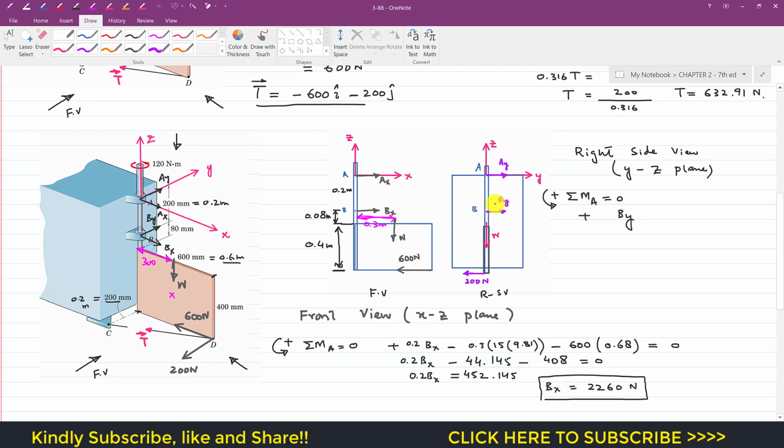and the perpendicular distance of this By from that point A is again 0.2. This is 0.2, right? So from here to here, this is 200 mm, or in meters this is 0.2 meters. So I will multiply it with 0.2, and then as we can see, this weight is going to pass through that point A, so it is not going to produce the moment about that point A since its perpendicular distance from that point A is 0. And the similar case is with Ay.